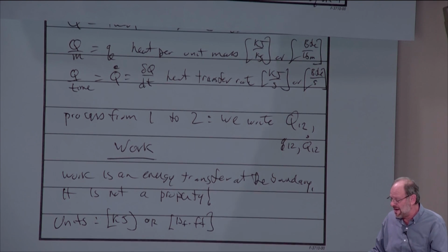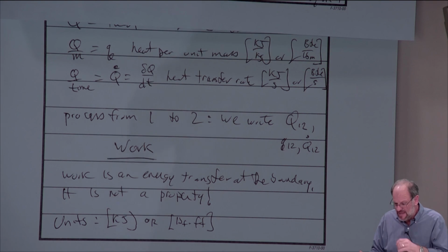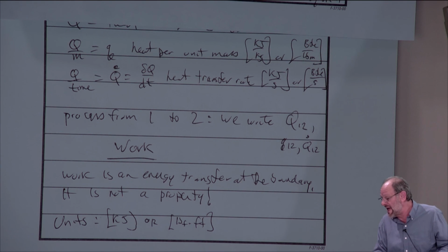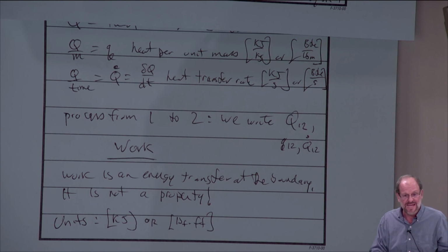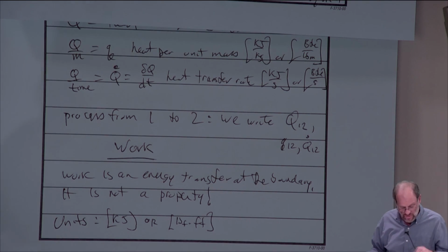So the pound-foot is sometimes the unit which is used for work. Now again, we could make a conversion into BTUs. If we're solving one problem and that problem contains both heat transfer and work, then we can't use pound-foot and BTUs in one problem statement. We are going to have to do some sort of a conversion, but these are nonetheless the typical units associated with work.